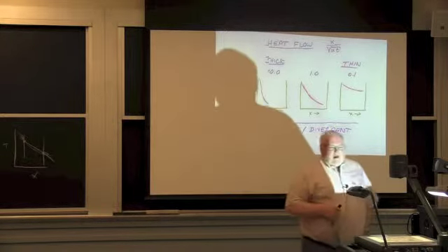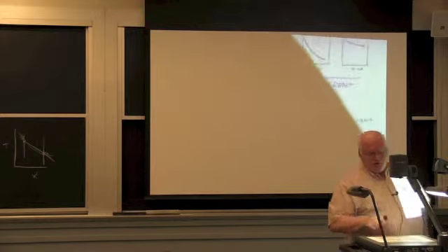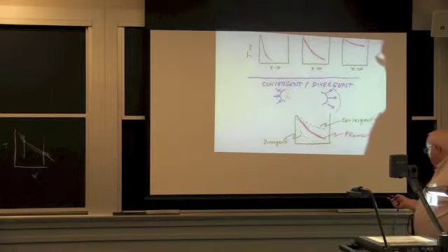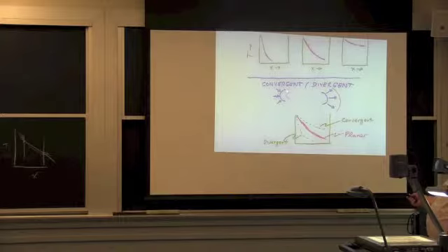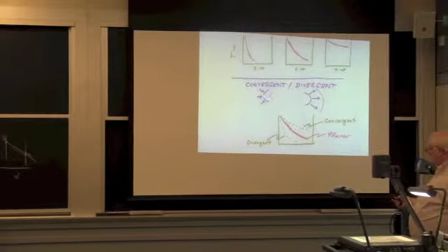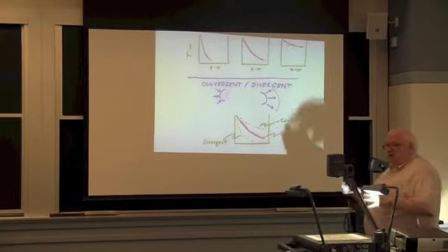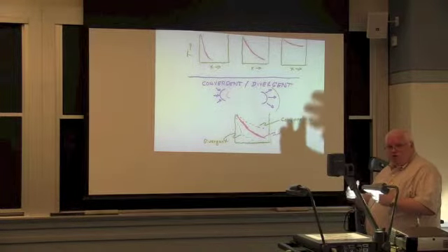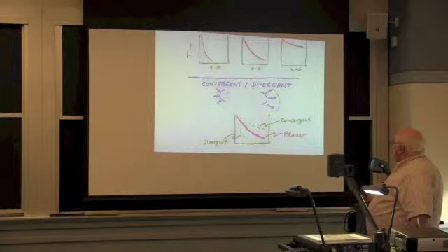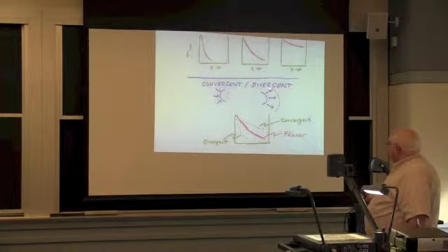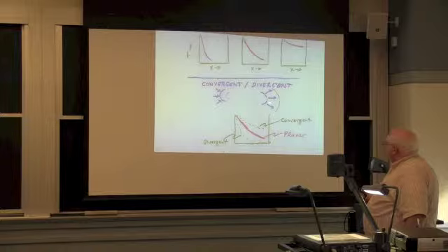Now you do have to worry about different geometries, and so you can talk about convergent heat flow and divergent heat flow. In convergent heat flow, I'm heating on the outside of a surface, and I have a smaller surface on the inside, so I might be heating the outside of a tube. And that means that I actually will heat up faster because I'm getting a smaller area to accumulate the heat. In divergent heat flow, I'm heating on the inside of a tube, for example, or a sphere. And now I have to heat up a greater mass out here.